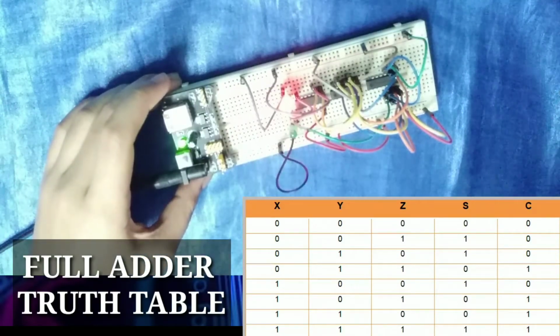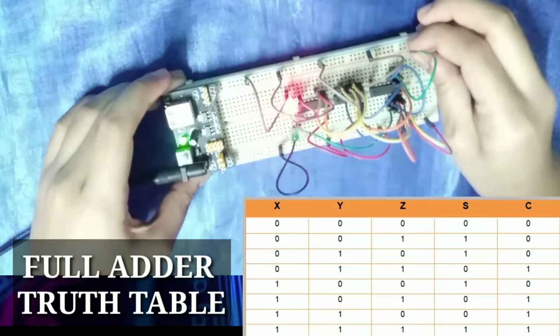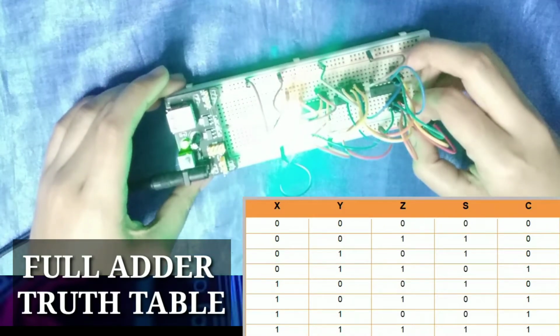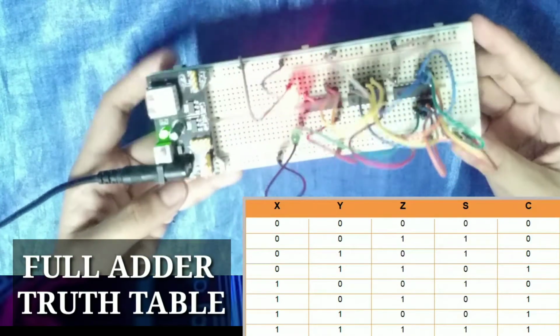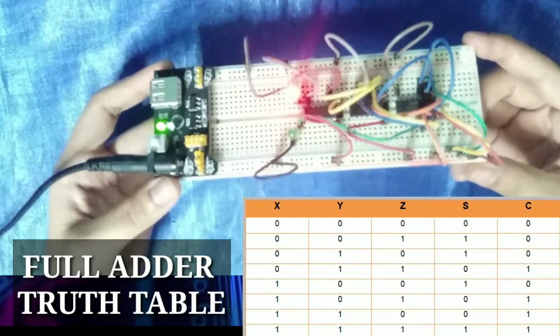Now, if both inputs X and Y are connected to the VCC or at logic 1, and only input Z is connected to the ground, as you can see, the output for carry, or the red LED, was turned on.